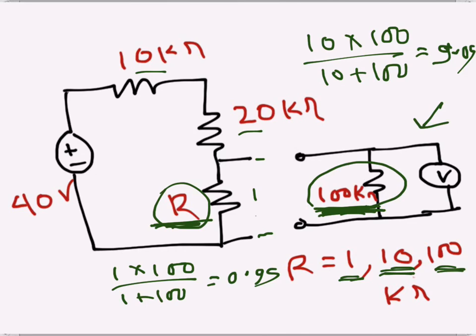But if the resistance is much less, like for the first case where it was 1/100th of the voltmeter's resistance, then the measured voltage was almost accurate. But if it is comparable, it's not accurate.